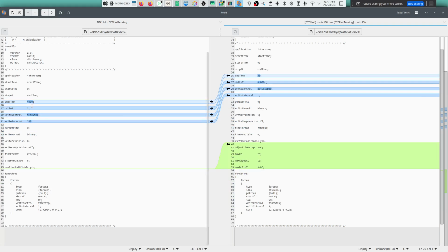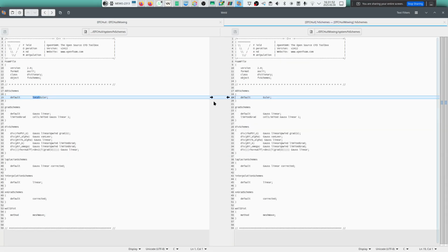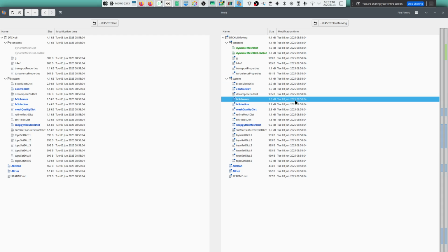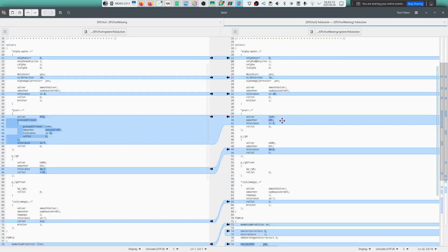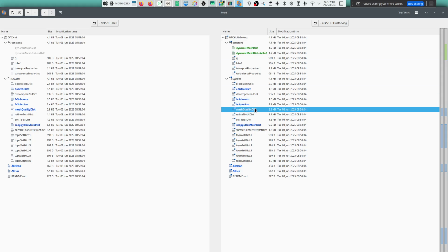For DTC hull you can use a steady model, but for this hull moving you need to use a transient model. The schemes are a bit different. Local Euler is only suitable for a steady case. Euler method for the time scheme needs proper transient setup, but usually there is only one, not many. Then you have the solution. You can see the difference. Try to check for yourself and ask. You can ask AI to explain to you bit by bit.